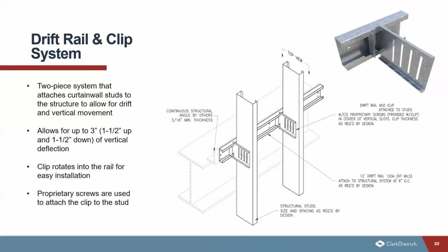Now, if you did not want to use this as a drift system, there also are locking angles that can be used to prevent it from sliding left and right. But as far as the studs go for deflection, they would use the proprietary shoulder screws that come with the connector, or they can use regular number 8 screws in the smaller holes to the right and left of the slots. And that way it would resist all movement. So you can use this connector as either a drift and deflection system, a deflection system, or a completely rigid system.